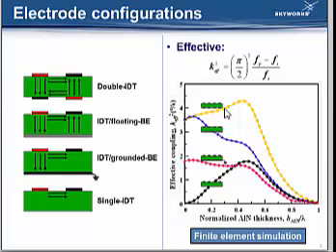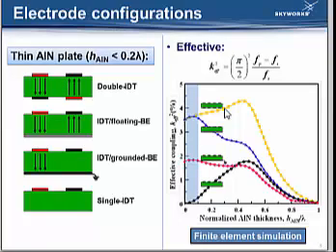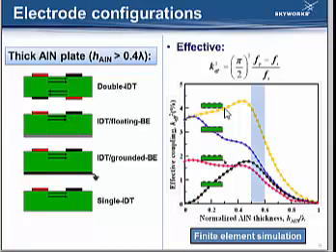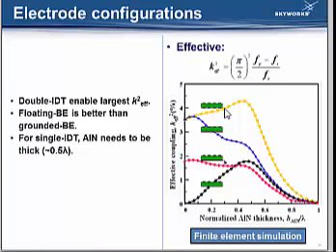we see the transducers can enable vertical and lateral excitation in the piezo material. When the aluminum nitride plate is very thin, the vertical field is stronger than the lateral, and if we only look at the vertical excitation, we see the excitation strength is proportional to the coupling value. Again, when the aluminum nitride plate is thick, the lateral field is stronger, and again, the coupling coefficient corresponds to the excitation level.